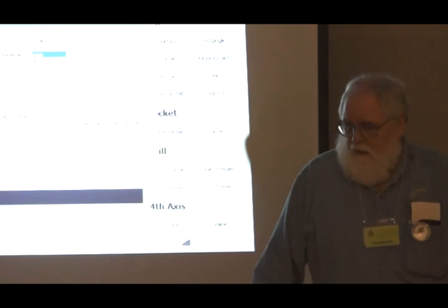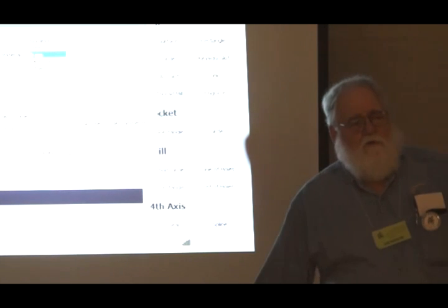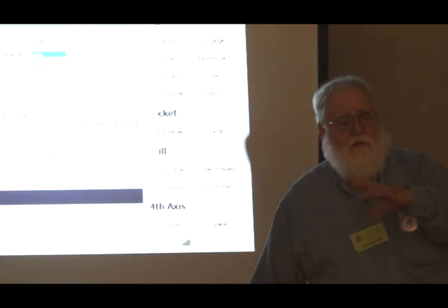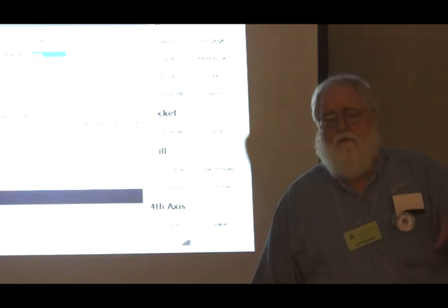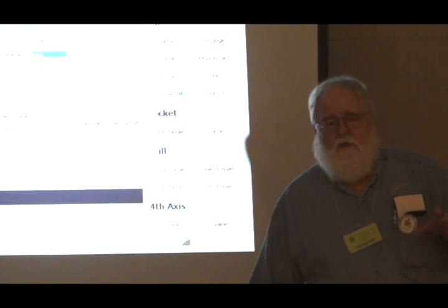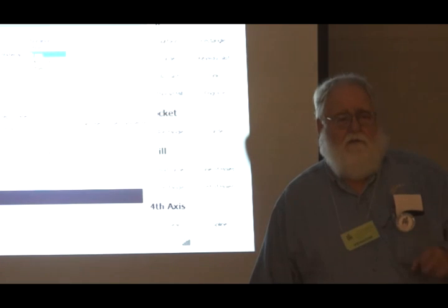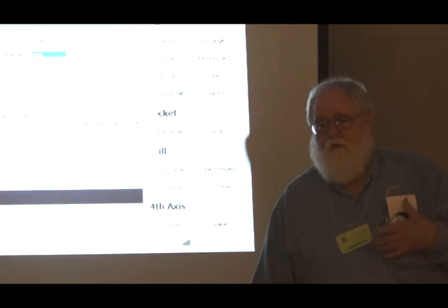I did a couple of surveys on the web about Z-step, when you enter a value for how deep you want to cut. Let's just take an example. I'm going to cut something 200 thou deep, and I say do it in 40 thou steps. Now, 40 thou steps doesn't exactly come out even to 200. I have two choices.